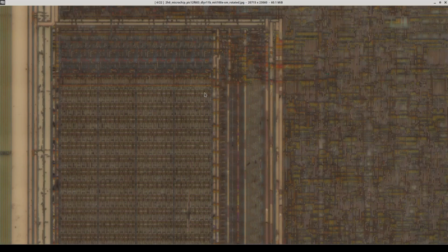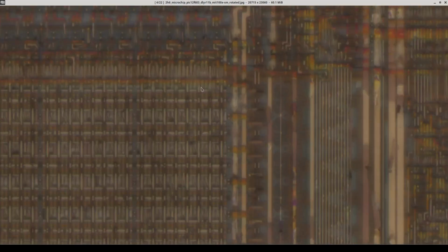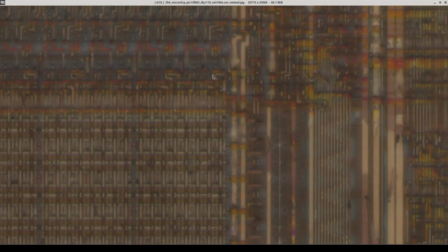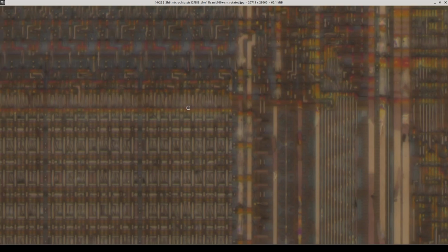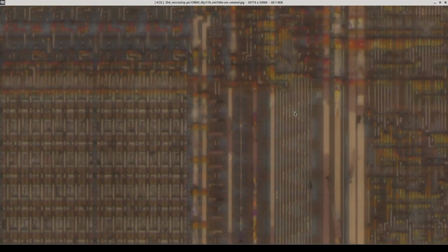So now jumping up to the poly layer, we can see word lines running horizontally across the array. The bit lines are presumably vertical, and in fact, if we jump up to the metal 2 layer, we can see some of the bit line structures here. Again, we're not taking too deep of a dive yet, just trying to get ourselves oriented with the overall memory structure. And then we see some vertical lines here on metal 2 that are going down into the row circuitry.